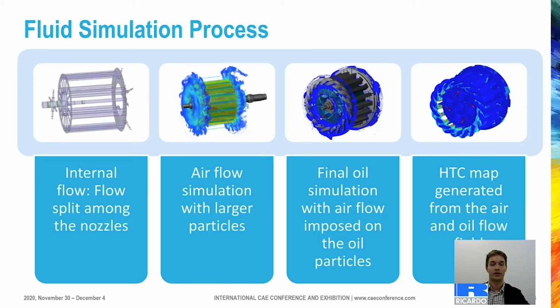The process of fluid simulation actually consisted of 3 different simulations. The first one was a quick run to determine the flow split among the different sets of nozzles, so that the internal flow does not have to be simulated in the final long run.